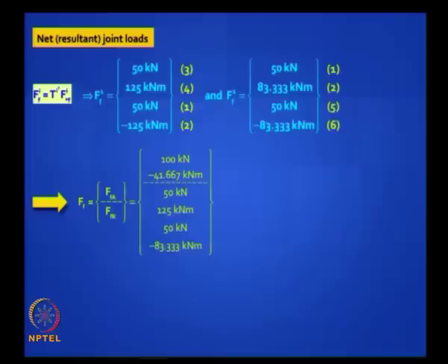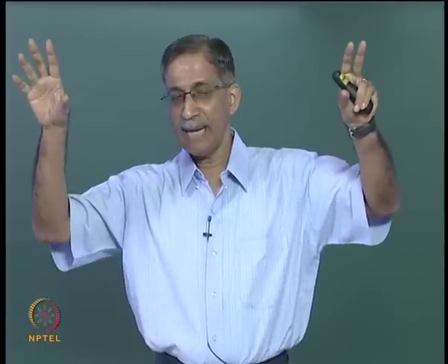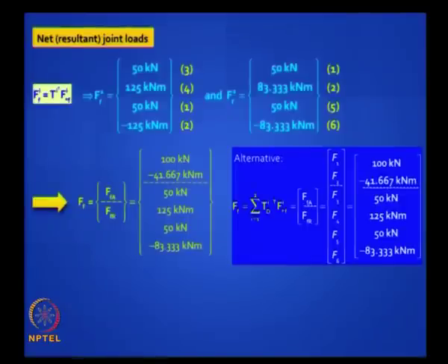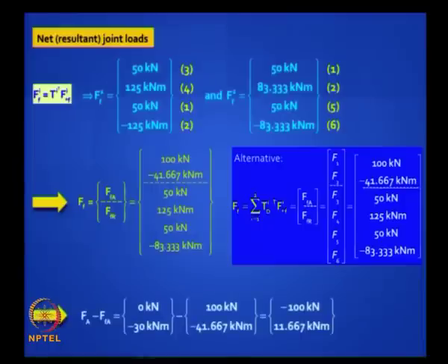This is a slotting thing, once you have shifted to the global axis system, you are matching the element with the structure. Does it make sense? Clear? Okay. If you want to do the TD approach, that is straightforward. You got your TD, take the transpose, pre-multiply, you will get the same solution without doing any slotting. So this is in a sense easier, but you are dealing with bigger matrices, okay.